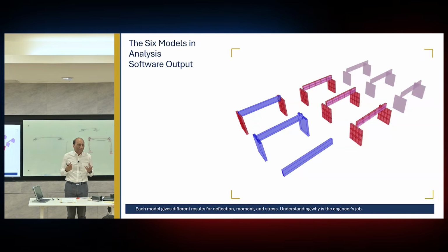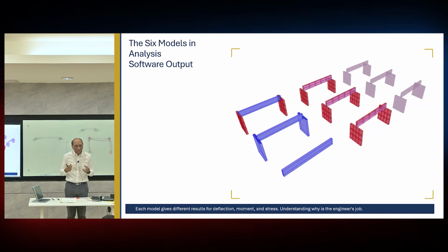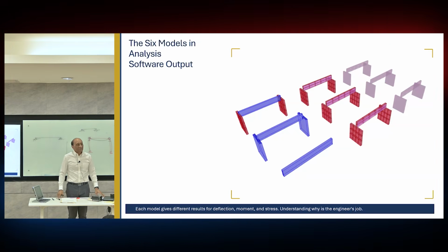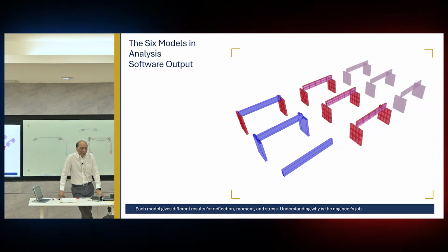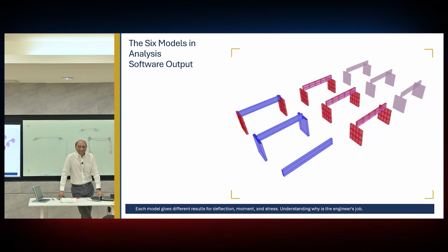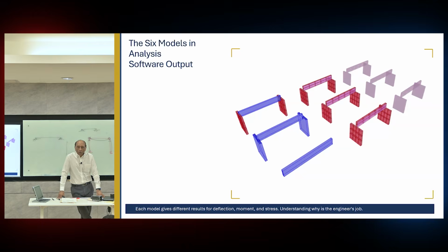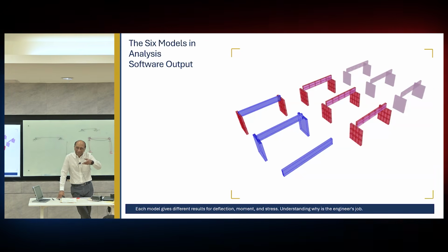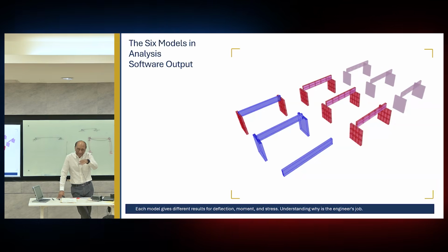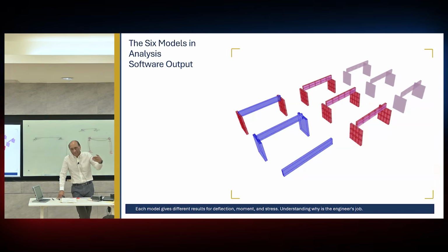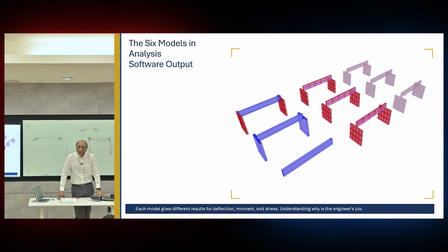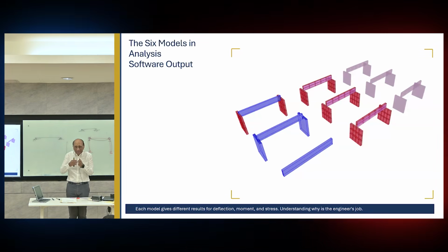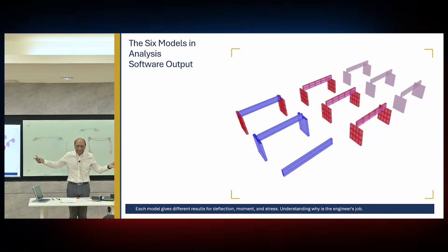And finally, I get a model, 6th model, which is everything is matching. All the meshing is accurate, but it's still connected. I still could not model the sliding behavior, overturning. It is still connected. The beam will never fall down this direction. It should fall down, right? It will never fall down because it's connected. It will never slide off the wall because it's connected, no matter how much load I apply. How much temperature I apply, it will expand, but will bring the wall together.